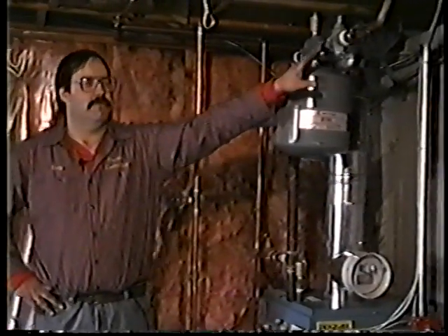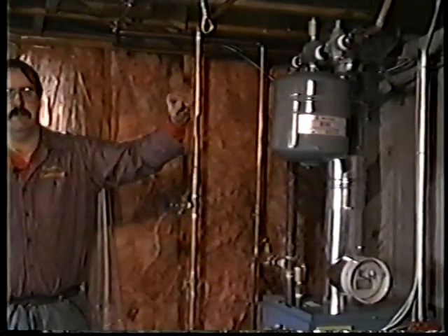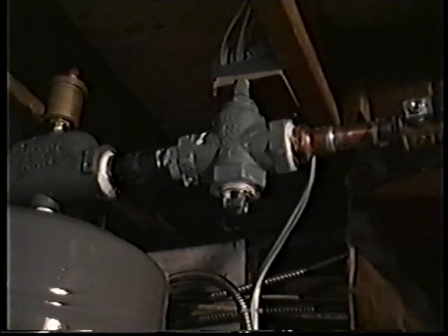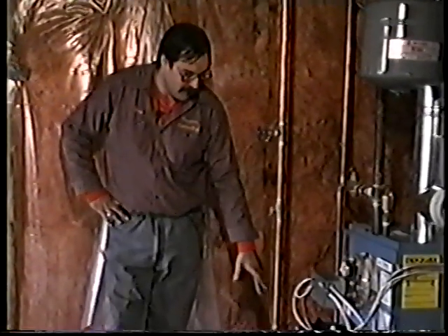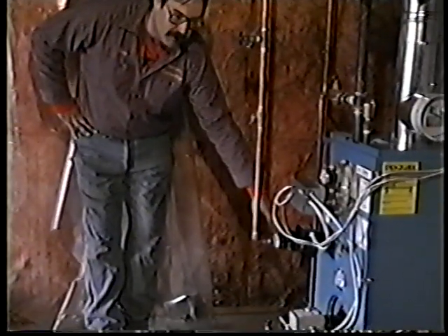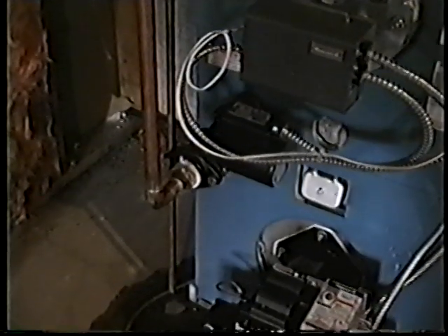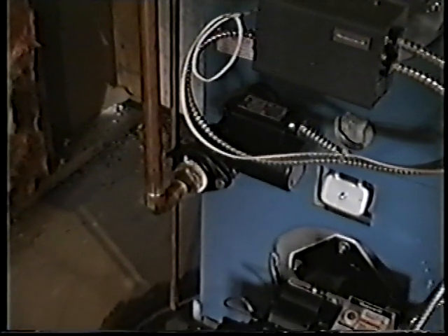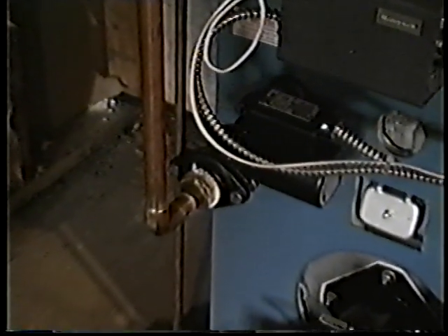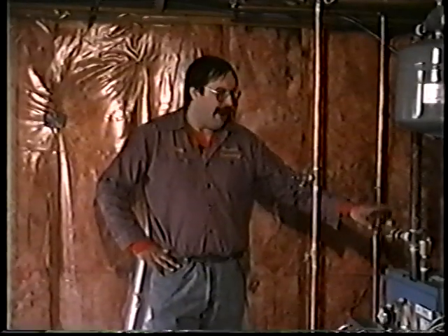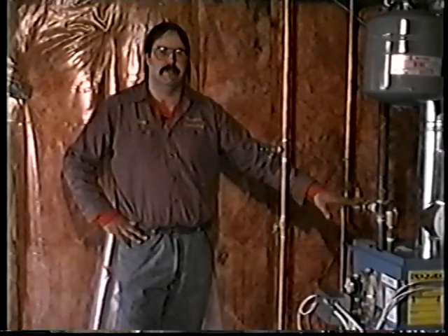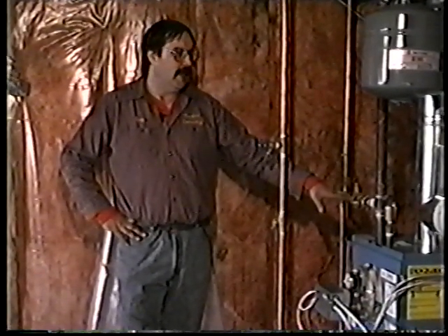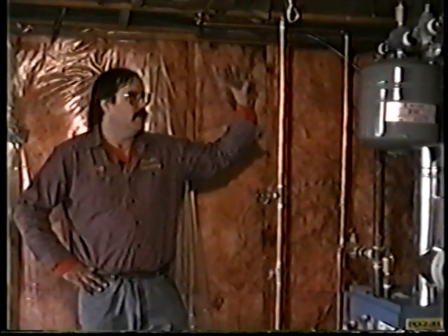This is a check valve that stops the gravity flow of the heated water through the system when the furnace is off. It comes back through the return system here to the circulator. When the thermostat calls for heat, the circulator is on, and it's running water through the radiators upstairs and back to the circulator. Then there's a backflow preventer to protect the water supply to the house from any cross-contamination that might occur. And the last piece is a power venter for the flue here.